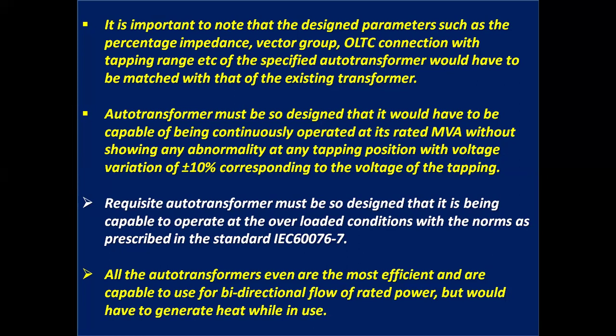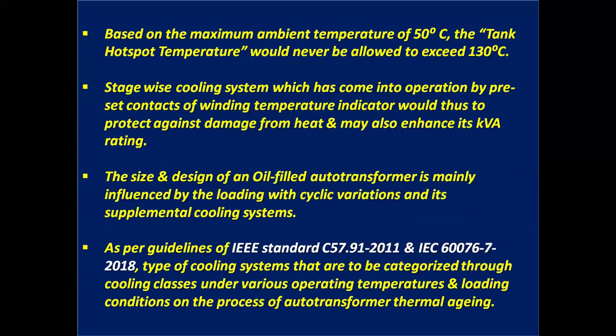All the autotransformers, even though they are the most efficient and capable of bidirectional flow of rated power, would generate heat while in use. Based on the maximum ambient temperature of 50 degrees centigrade, the tank hotspot temperature would never be allowed to exceed 130 degrees centigrade.